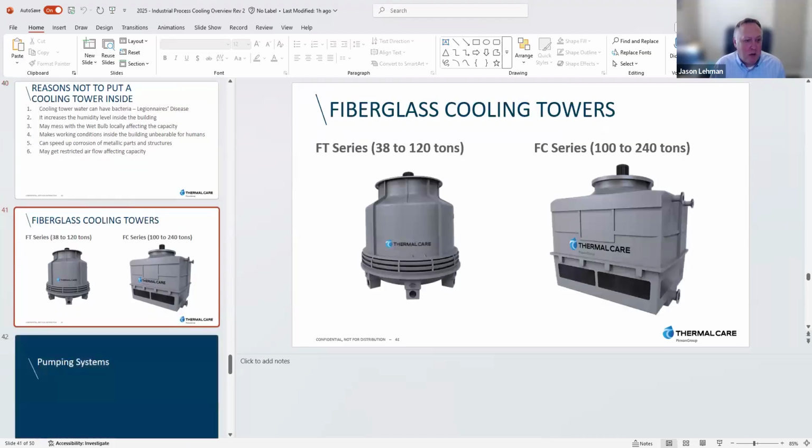But basically how a cooling tower works is, and these are a couple of our cooling towers. Water comes in the top. It's through the inlet here. There are nozzles that distribute it through fill, which is plastic that has a lot of surface area. There's a fan up here that pulls the air up, and the water evaporates off the fill, cools the rest of the water. It's like getting out of the shower and having somebody blow a fan on you. You get really cold because the water's evaporating off your skin, pulling heat there.